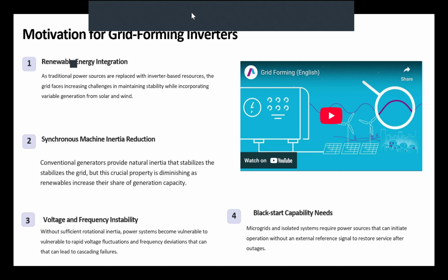Now it's not connected to the grid, it's separate, like an island, separated from the rest of the grid: islanding. When you have such a situation with inverters in islanding mode, they are disconnected from the grid, and they can't work in grid following, again because they need a reference and they don't have it. So all that together is also a kind of black start situation.